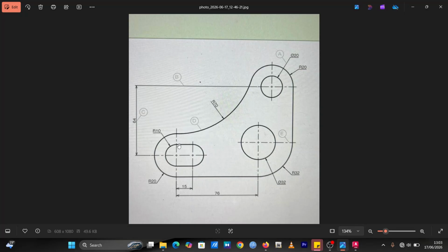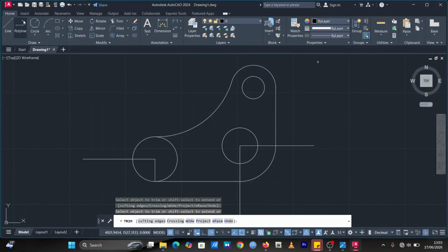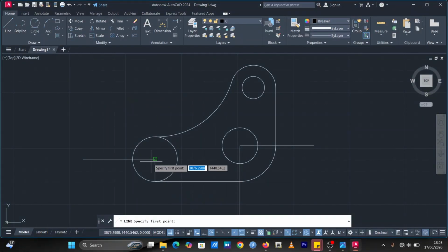So now we are going to draw this inner circle over here with smooth edges. To do this, we know the distance from the main center to the right here is 15. So you first measure your 15. You are going to pick your line tool, you stand at this center, and you move here, you measure your 15, you press enter. So we are going to have this.